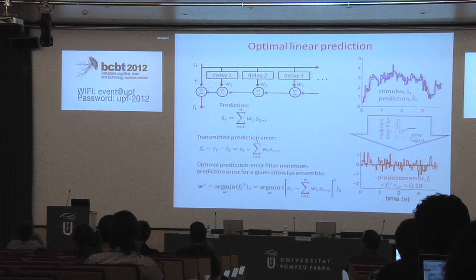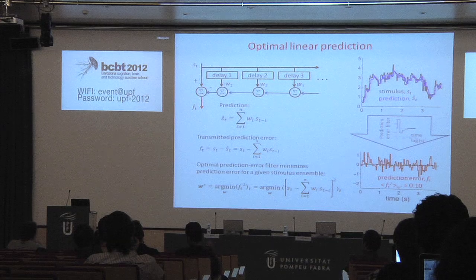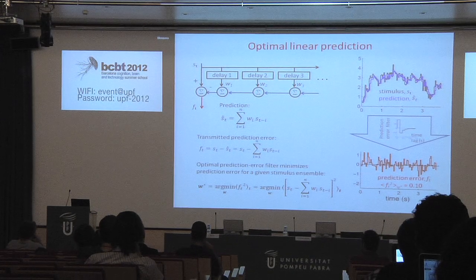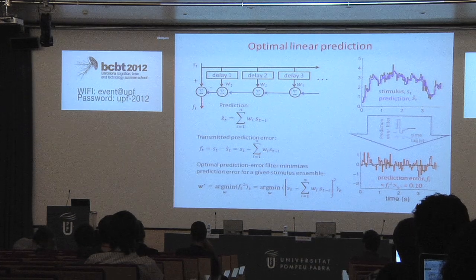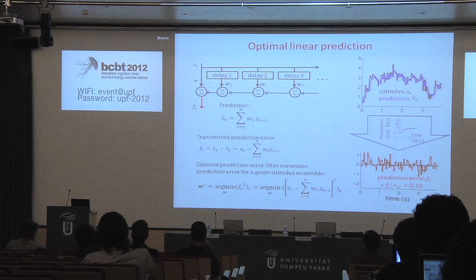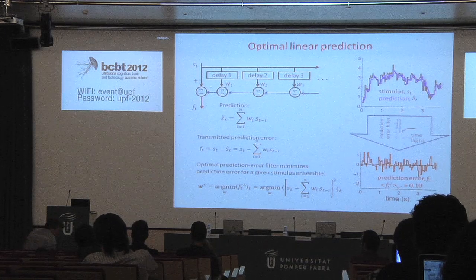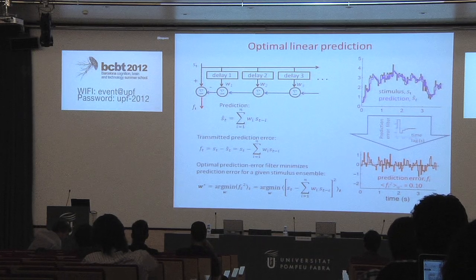Okay. The other part of the answer could be that in practical implementations of predictive coding, especially when there is communication noise, the way people deal with it is that the subtraction is not done perfectly, and you inject a little bit of a leftover of the original signal in the transmission. And if you reconstruct it with the leaky integrator instead, then that actually allows you to overcome some effects of noise, but also keep track of the background level of the signal. Okay? Any other questions?